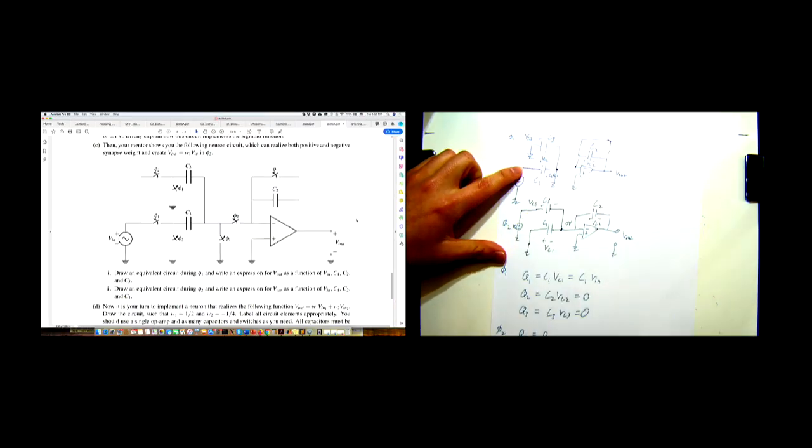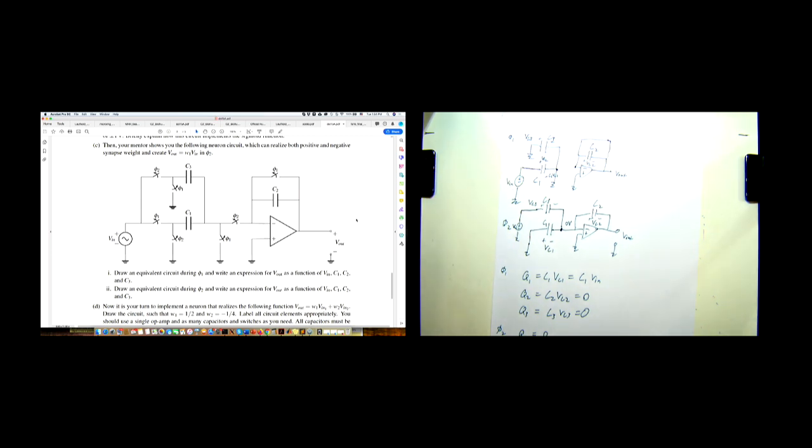So in general in a capacitor, when you have a voltage across it, you have a net charge which is equal to C times V, the voltage across. So it's plus that net charge on the positive side and minus that net charge on the negative side. The positive is the side that has bigger potential. In this case, V we assume is positive, so it's bigger than 0.